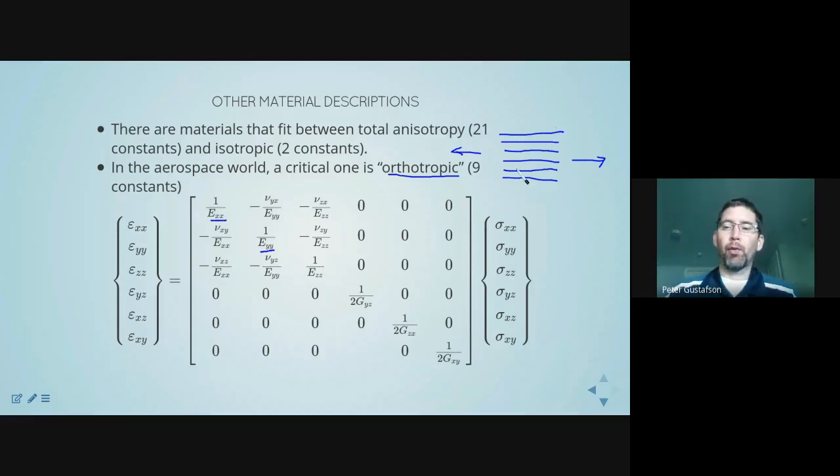In this case, we would have yet a third response, or perhaps the response in the third direction would be quite similar to the response in the second direction. Anyway, as a general statement, it could have a third modulus in the z direction. And then Poisson's effect still governs, but it governs with different coefficients. In this case, you can have 1, 2, 3 unique Poisson's ratios. So we have 3 moduli, 3 unique Poisson's ratios.